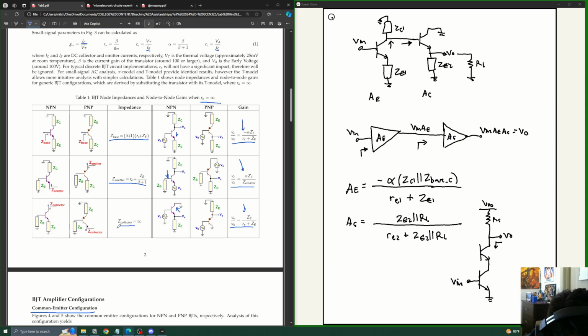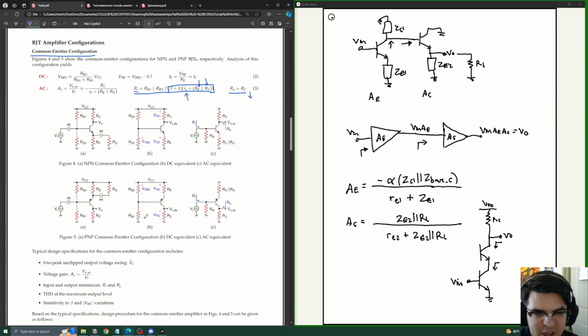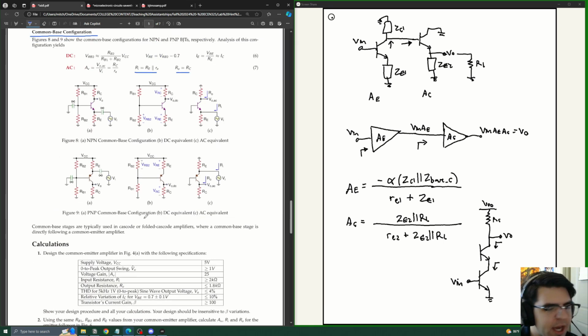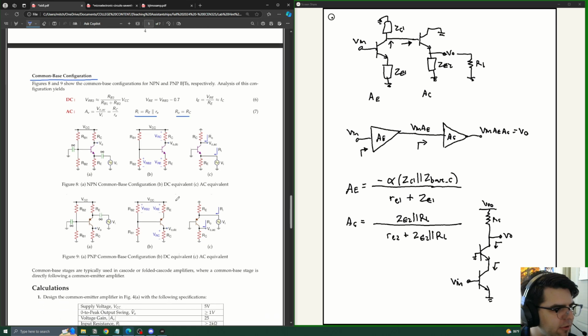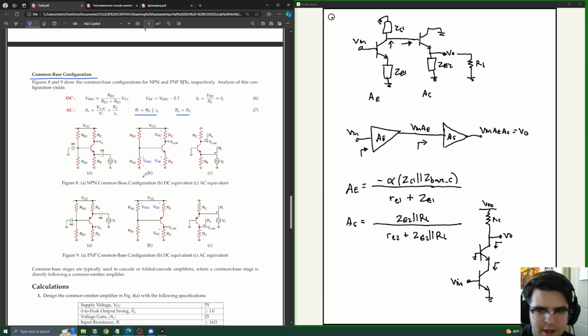And the deal is that we've got two infinities nested into each other. So the output impedance is like infinity squared. So the output impedance is ridiculously high, and because of that, that also makes the gain extremely high. So that's where this situation shows up: normally we have the common emitter followed into the common base, leading to this Cascode configuration, which gives us really high gain for just these two transistors. And it's got a couple other nice effects that you would cover in higher level courses. So that's where this configuration shows up a lot.